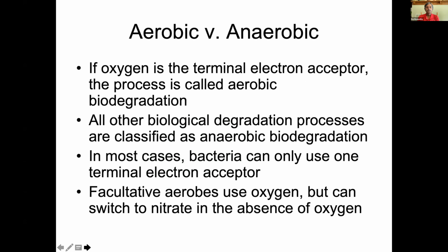Under anaerobic condition, the anaerobic bacteria can also degrade. So you need to provide various electron acceptors like nitrate, iron, sulfate, or methanogenic condition, or fermentation condition could also be used under anaerobic condition to remove some of the compound.